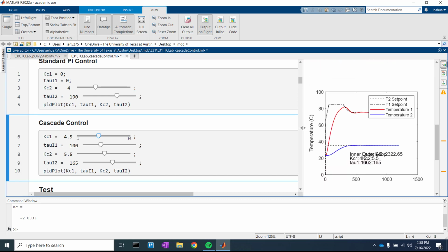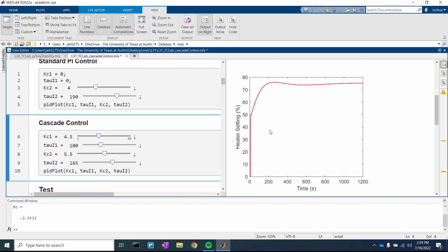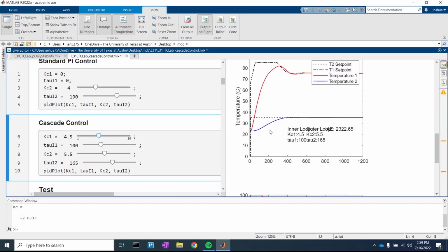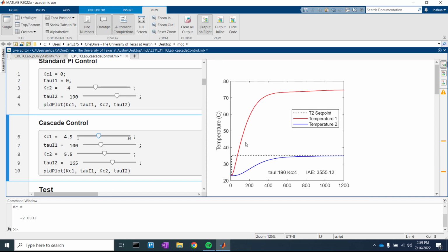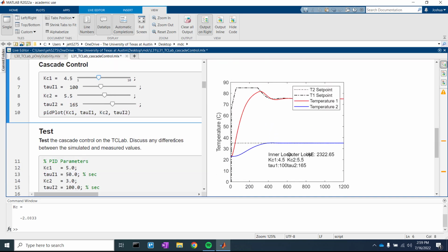Okay, we're doing better. Still don't love that now it's in the way of something else. It's in the way of us seeing kind of the end performance. But we can still characterize that first bit, and that's usually where most of the error is going to be. So we think through a cascade control. Again, what's happening is we have a set point change, and that set point change is changing our temperature 1, and temperature 1 is in turn, because of how close the heaters are, affecting temperature 2.